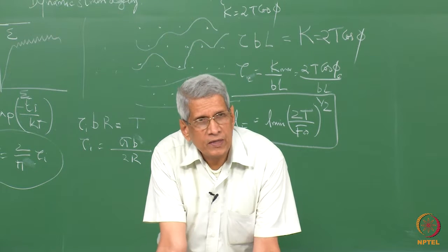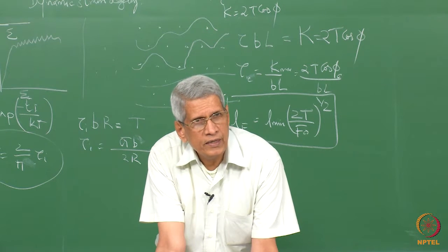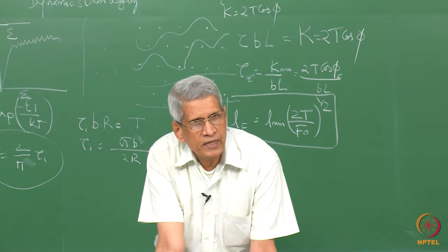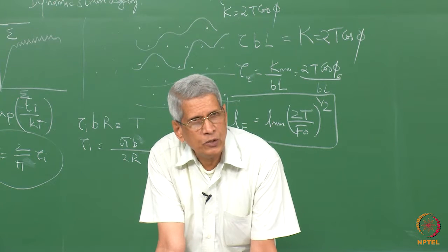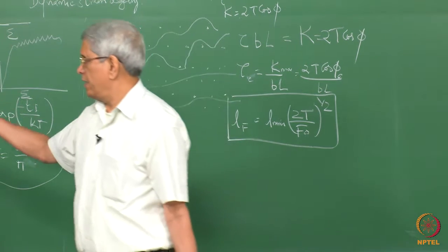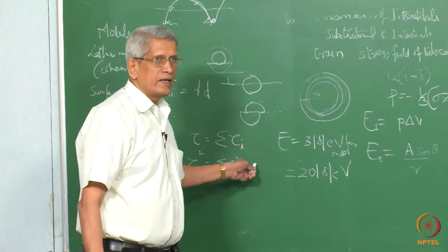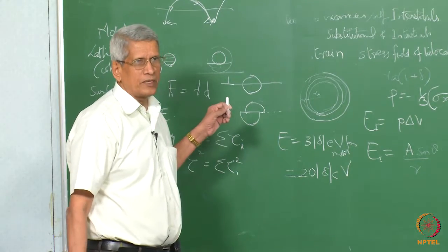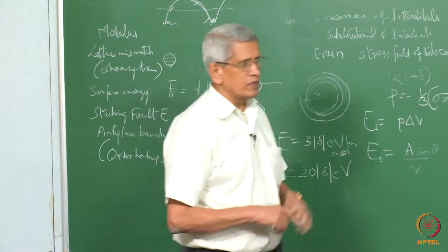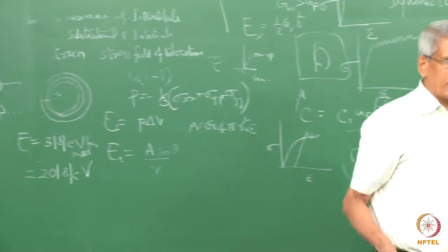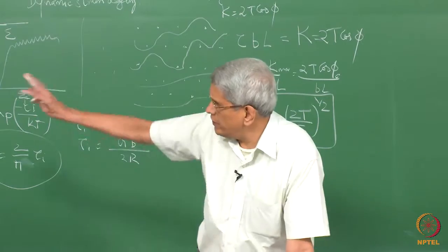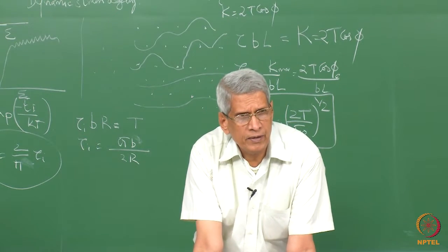Where the stresses are vastly different, a simple addition is taken. When they are all of the same magnitude, they are squared, added, and the square root of the mean is taken. This is a standard procedure followed in other branches of science also. This essentially tells about the hardening.